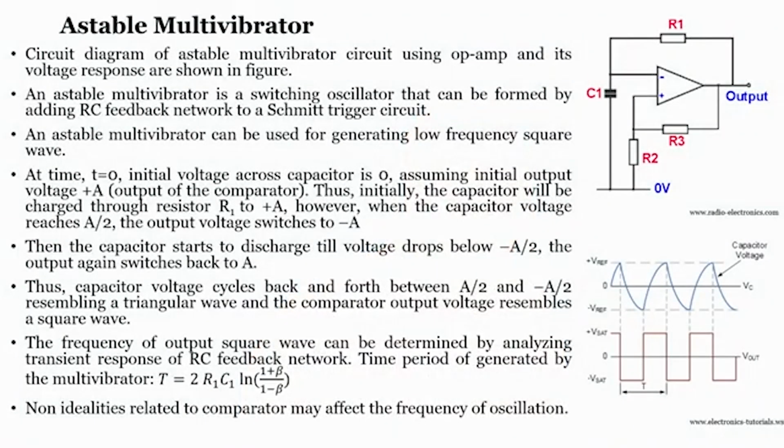Now, when we look into the astable multivibrator circuit, if you remember correctly, our inverting and non-inverting Schmitt trigger circuits, we can see here that one part of the design is similar to our inverting type Schmitt trigger, isn't it? When you recall our Schmitt trigger circuit, it is using positive feedback. Even in this case, you have a positive feedback connected with a resistance R3 and one more resistor R2. Whereas for the inverting Schmitt trigger, the input is connected to the negative terminal.